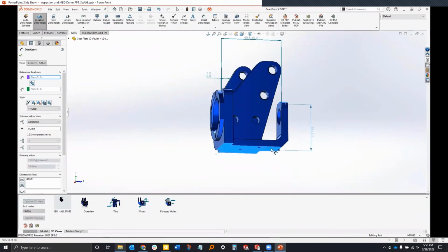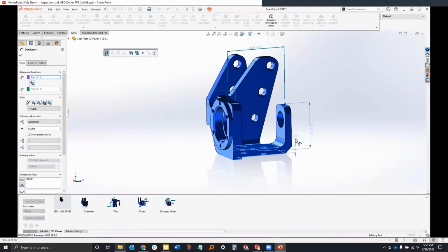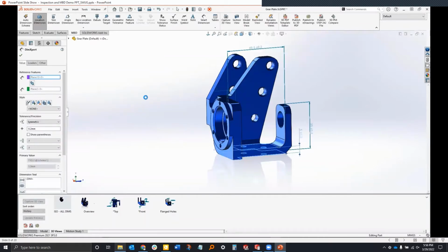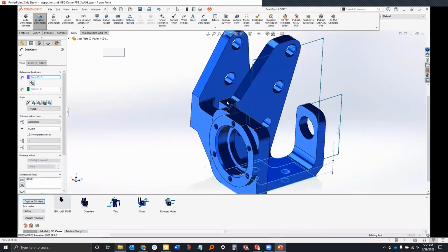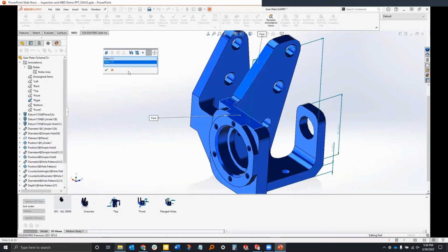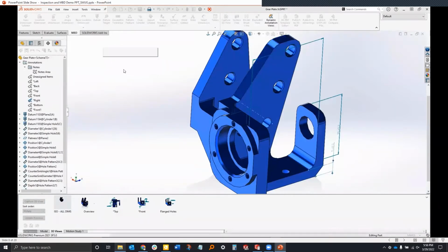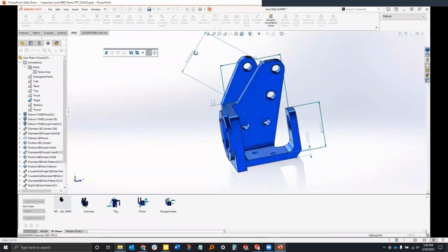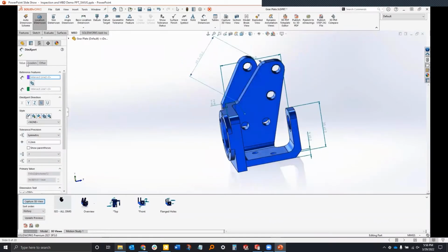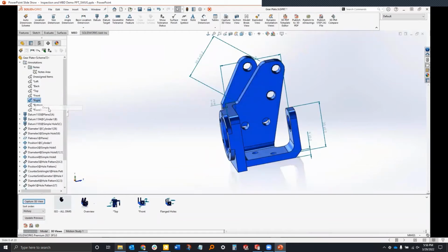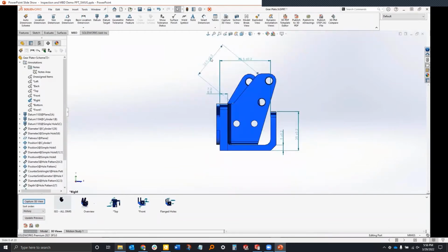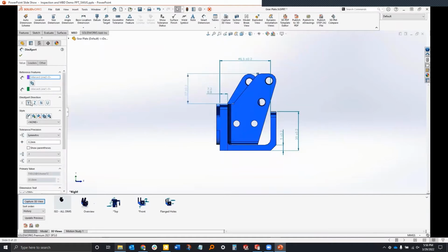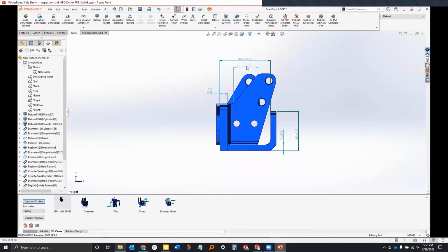So as I finished up creating these dimensions, the next thing that we're going to see is if we have something that is potentially at an angle, perhaps we want a dimension going to an intersection of angled sides. Well, we can actually set that up in MBD. So that's actually what I'm doing now. And as an end result, the dimension that actually produces is going to be from those intersection lines. I can go ahead and make further modifications in Y, Z, normal to, or even a user-defined direction in order to change and specify that specific dimension.